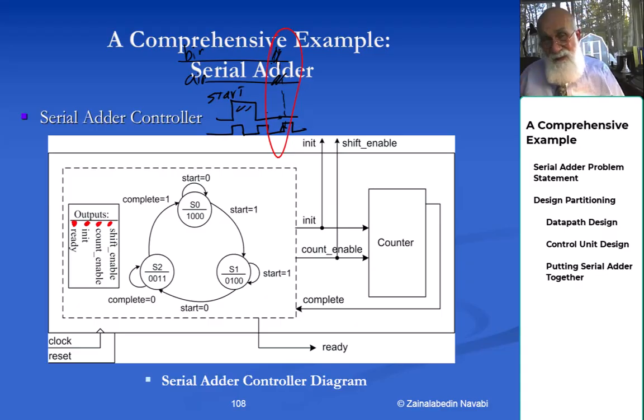But then I have, in addition to the shift register that I have to control, as soon as I get into this state, state 2, that I'm prepared, I have to make sure that this state repeats 8 times. Therefore, what I do on this side, I put a counter that, as I am initializing my flip-flop, my counter is also initialized to 0, 0.